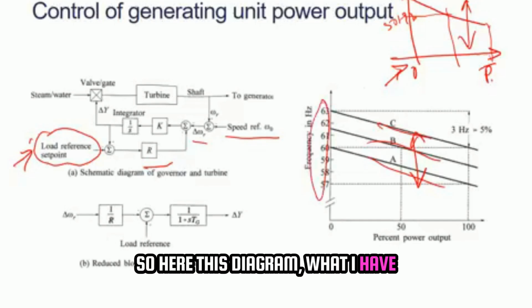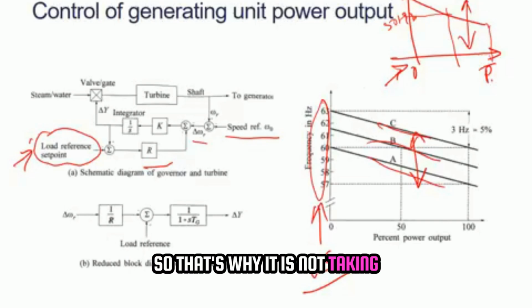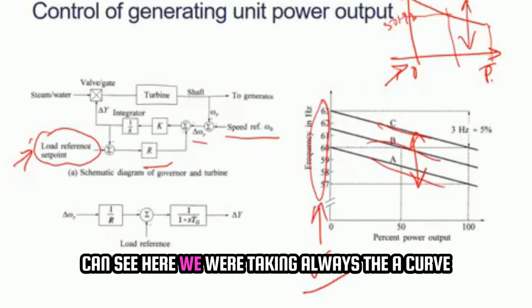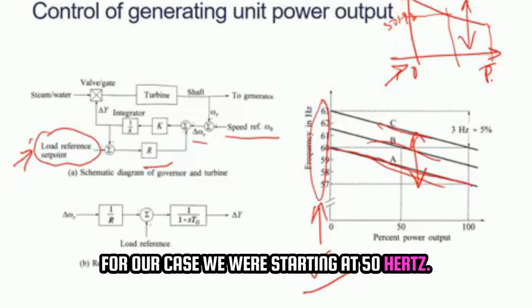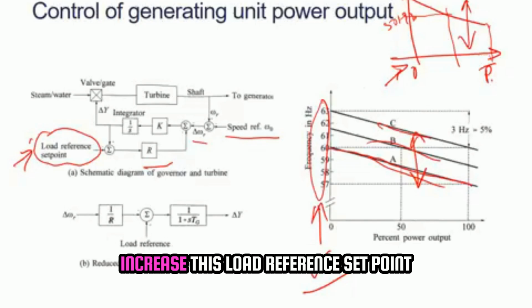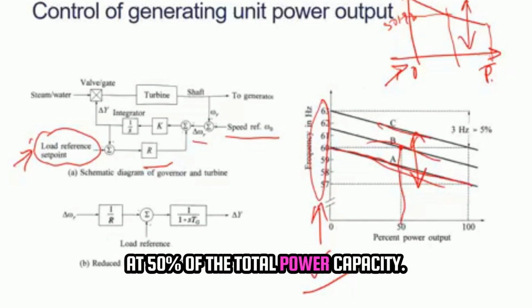This diagram is for the US based system, so it takes the nominal as 60 hertz, but you can change that value. In the US it is 60 hertz, so we were always taking the A curve starting from 60 hertz, while for our case we start at 50 hertz. Now you can increase the load reference set point, and then you can see that 60 hertz comes at 50% of the total power capacity.